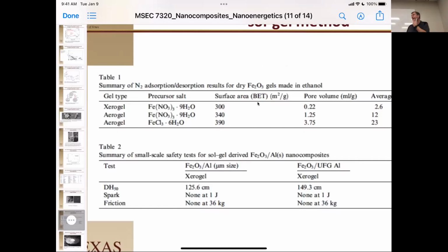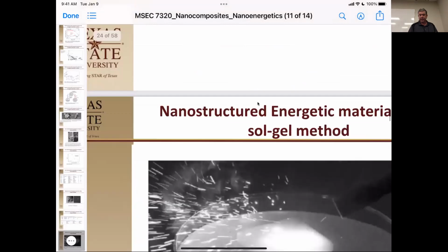What's the test setup for that friction? Oh, let's see. I want to say it is literally 2 pieces of the same material, not rubber. It's going to be a harder material. They put a weight on top of it, they put some material in here, and then they slide one of them. There's also another setup where they actually have a pendulum that slides across. But I don't have any pictures of that.